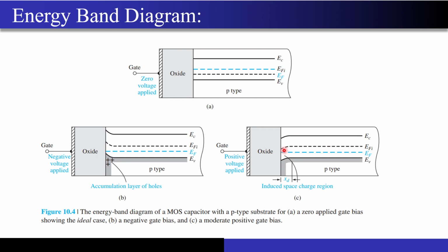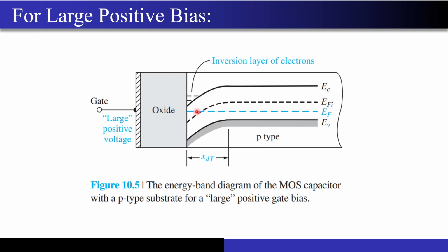So that means even near the surface, your material is actually still a p-type material, right? It has not inverted. But what if I keep on increasing this voltage? What is going to happen? This band bending that you are going to see, right? The moment I apply a lot of voltage over here, the more these bands are going to bend, right? So now the more these bands bend, this will cross this point at a certain instance, and this is what I am showing over here.